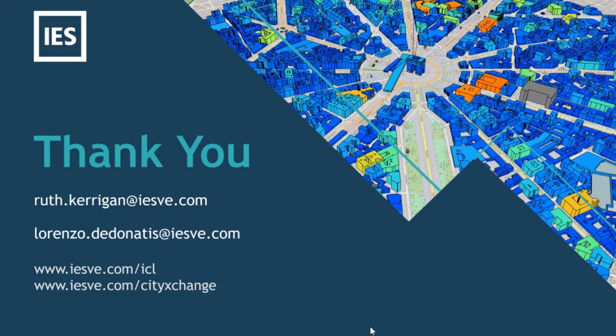Salman is also asking about other factors like rain and snow. The weather file doesn't simulate the effect of rain or snow on the photovoltaic panels. So these additional factors can be put into the calculation as an overall inefficiency factor. There are usually calculations and estimations for specific regions, and also suggestions from the manufacturer itself, because the model won't simulate rain or snow on your panels, but you can take that into account through so-called inefficiency factors.